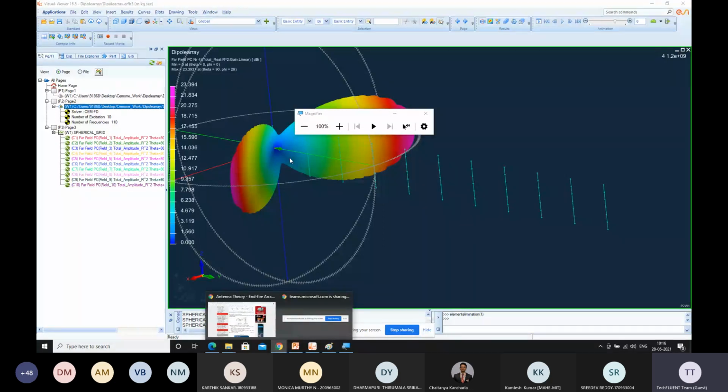So in practical, what happens is, sir, whatever dipoles you will be having, right? You will actually be having some SMA ports or coaxial probes for feeding it, right? Yes. So we'll actually be using a splitter from an excitation source, where we'll be splitting the channels to 8 or 11 based on the connections we have, and then we'll excite it. So you can excite it all at once, so that you'll be getting a pattern out there. So this is a resultant one we have to analyze. Whatever we are getting is a resultant one only, sir. Correct. Okay.